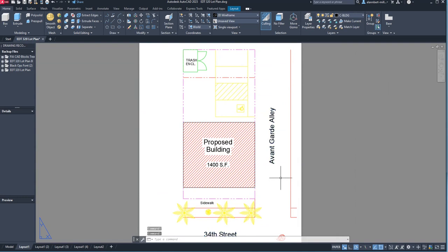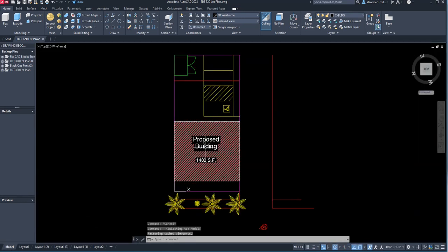But any text that you put in model space, you cannot erase from paper space. I cannot erase them because I cannot select them, because they're in model space. I can select this and this, but anything inside model space cannot be selected. This text here is inside model space. All you do is go to model space, and you will see the text here. All right, just make sure.